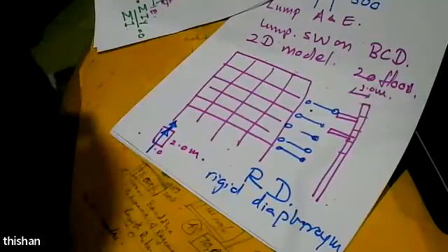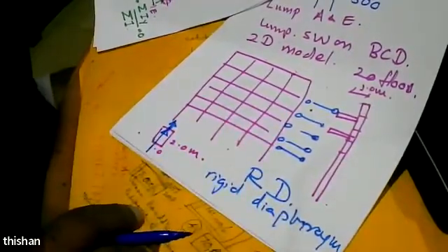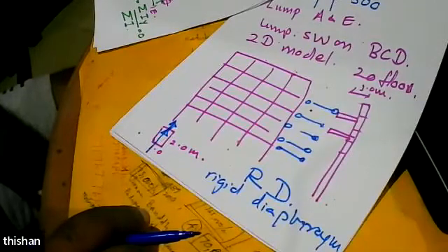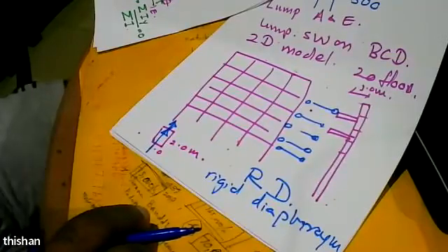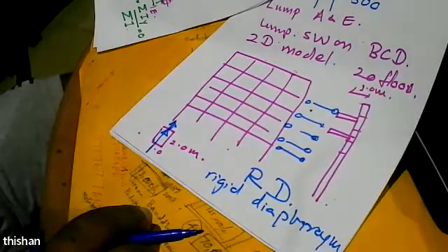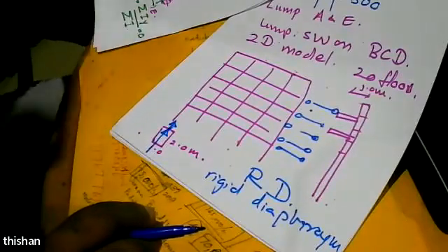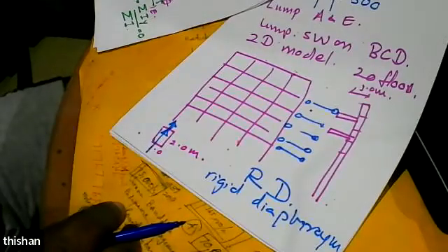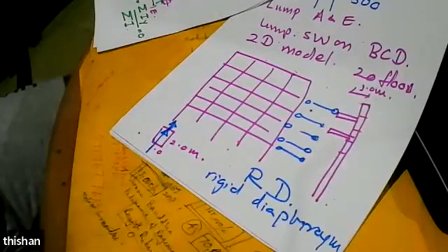And so you start to generate a floor like this and generate a column like this and then connect them. Again, you can see the mathematical model is very different to the 3-dimensional structure that you want to analyze. Right. Now in the actual structure we get shear walls. We represent them by using rigid arms so that any deformation at the end of the shear wall will be the deformation in the slab.